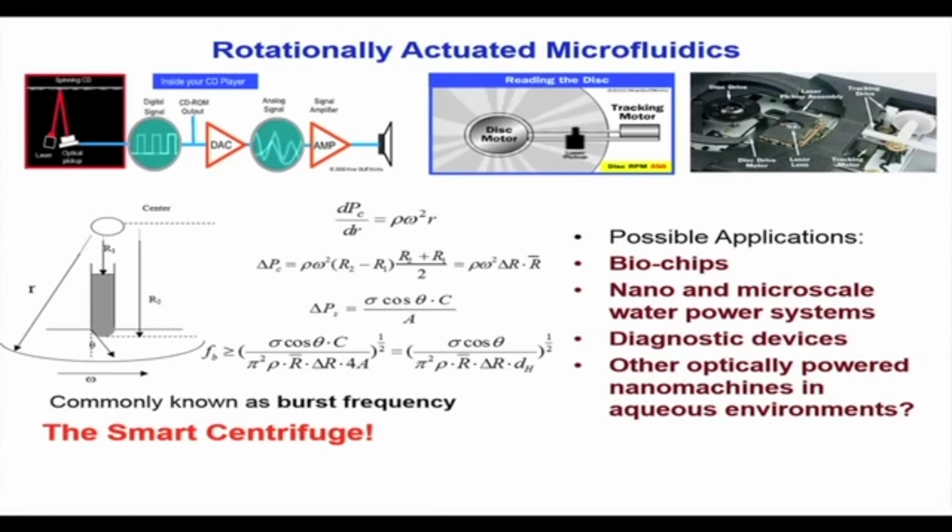Can you tell, is it radially inwards or outwards? It is radially inwards. Just draw the tangent to the interface, you see the tangent to the interface is inwards. So this is like a typical hydrophobic type of meniscus where the surface tension force is inwards.